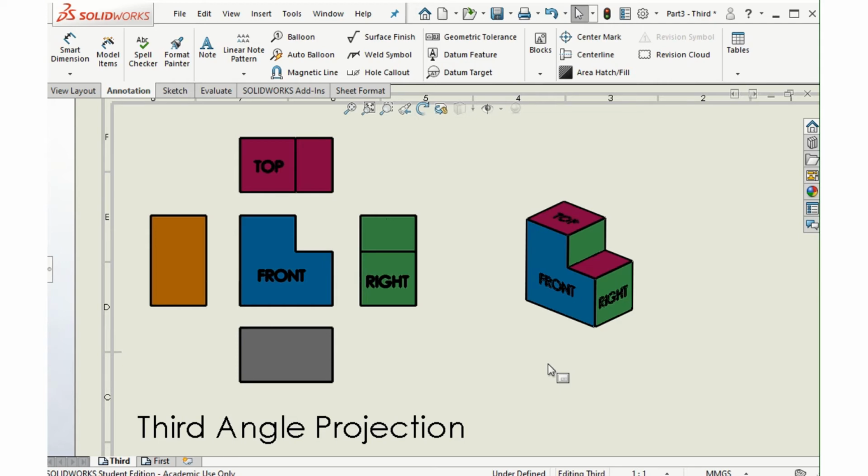One of the first things you should do when you pick up that drawing is have a look to see if it's first angle projection or to see if it's third angle projection. And if you are lucky enough to get a three-dimensional image with your drawing, just double check it, because again, not everybody does this, not everybody checks it. And I've picked up drawings when I've worked in a manufacturing environment where the drawing states it's in third angle projection, and when you look at it, it's actually been drawn in first angle projection.